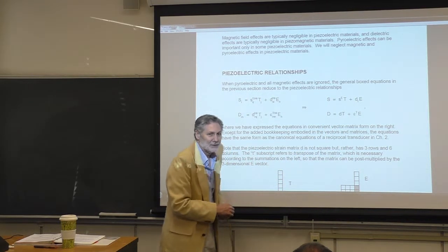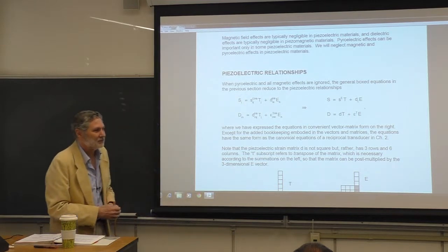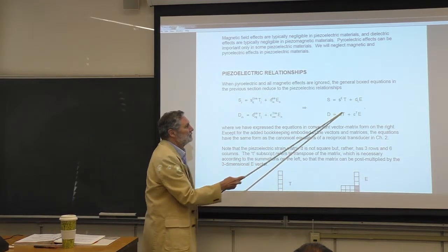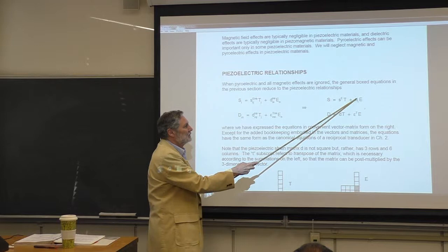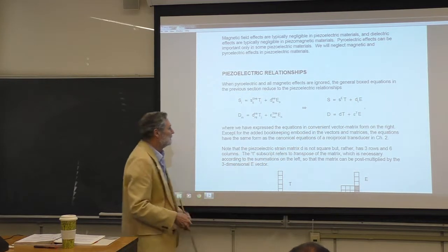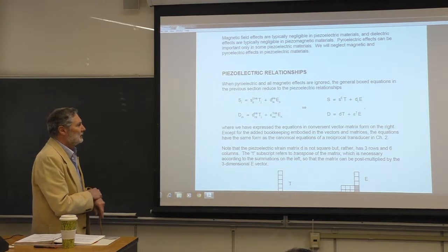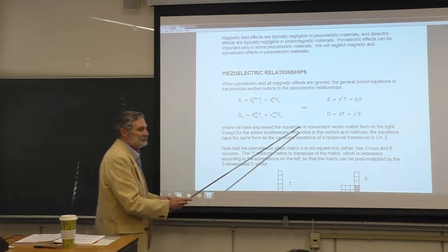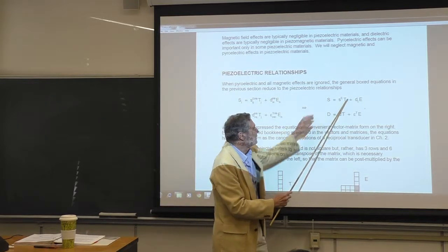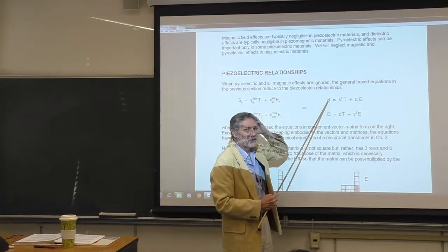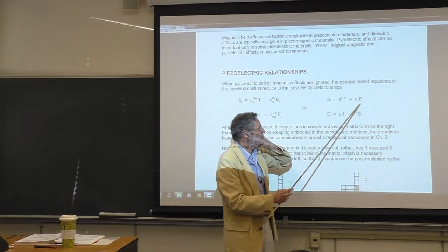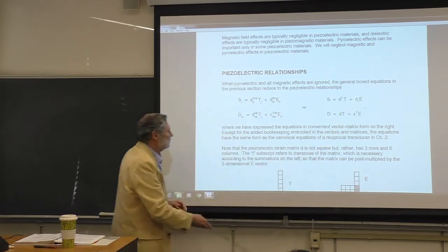And what kind of a transduction is it? It's reciprocal. You see this coefficient is the same as that. So these are actually the form of the canonical equations. And with bookkeeping, these aren't scalars. This is a 6-dimensional vector, and these are matrices here. All these lowercase things are matrices here.